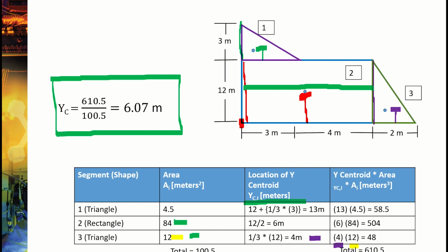So if you got that your center of mass had been y equals 17, that would tell you that the center of mass of your system is up here, which, how could that possibly make any sense? Because that is not even in the shape in question. Had you gotten your x center of mass was something like over here, you should look at that and think, that doesn't make any sense either, because that is way to the right, and I can tell that most of my mass is to the left.